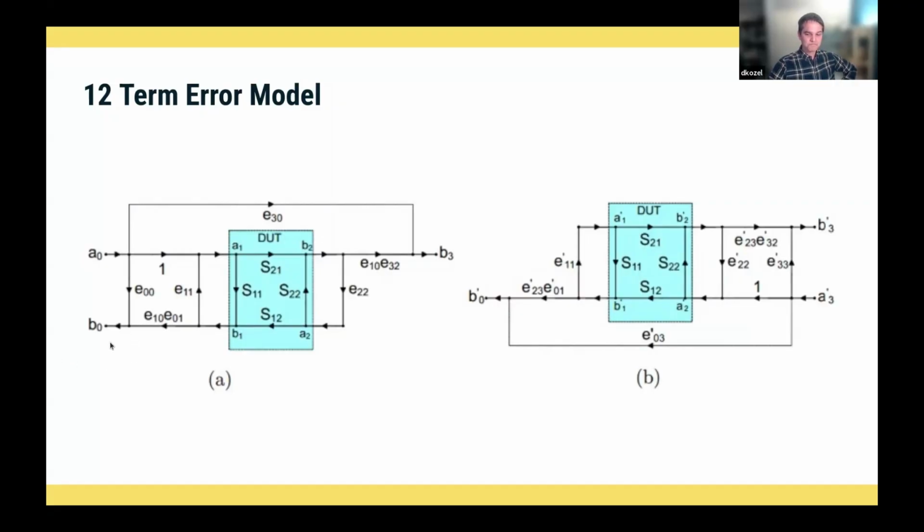If you've ever, what's a good example? If you ever unplug the antenna from your HT and then have somebody transmit right next to you, you're probably going to be able to hear it anyways. There's signal leaking straight through your device, not just through the coax, but straight through the case, through the shield of the coax, right into your receiver, into the circuit. So we have some forward leakage. We hope that all the power going forwards is getting there, and that there's some accounting for the loss.